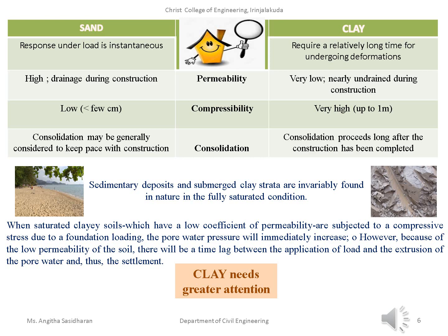But because of the low permeability of the soil, there will be a time lag between the application of load and the extrusion of pore water, and the settlement happens. So clay needs greater attention. If you're talking about consolidation, we'll be much concerned about clay soils than sandy soils.